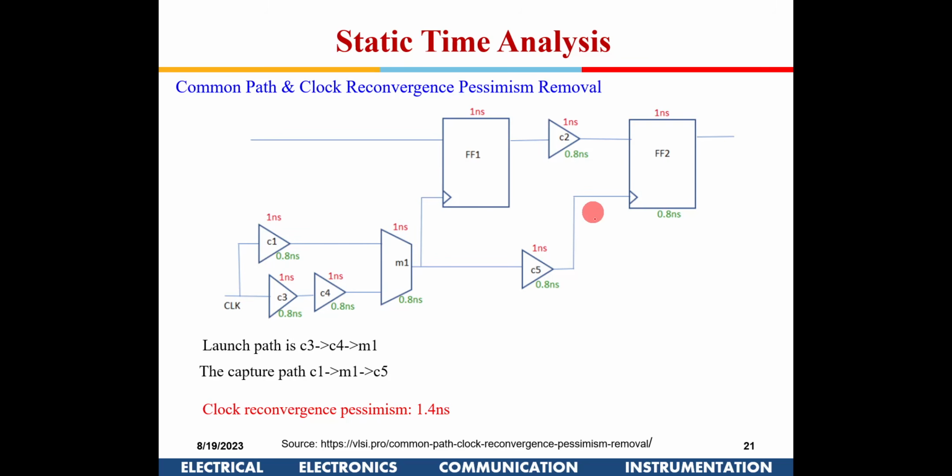So it won't actually make a difference in this circuit, okay, because this clock starts from here. So all our computations of slacks won't matter, right? But it will only make a change if for one path you are taking here or if you are taking here, right? Then it induces an error, pessimism, into the analysis, okay. As long as you are taking either this or this, only one of the conditions here, the clock is coming at the same time, so this analysis won't get disturbed, okay. You will get a realistic analysis, okay.